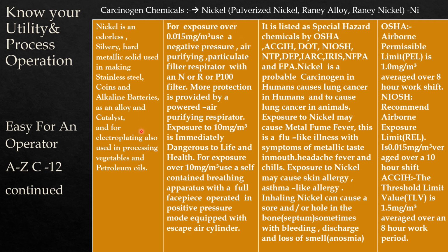Persons who are working in electroplating plants, normally in small scale industries, also in stainless steel production and battery companies, where it is used as an alloy and catalyst in the factory. A person who is exposed to nickel has to be very careful because the limit value is very low. So use PPE to avoid nickel vapor contact and exposure to this carcinogen and dangerous chemical.